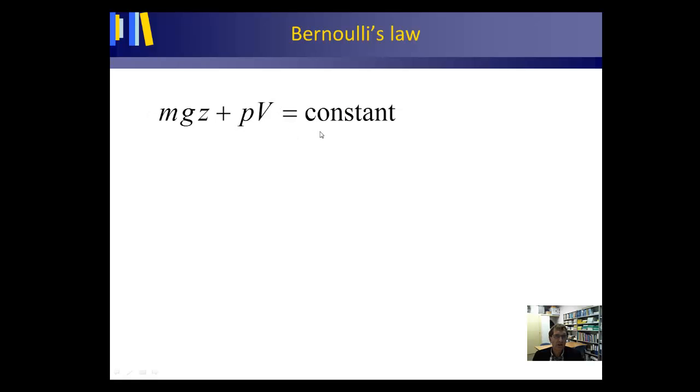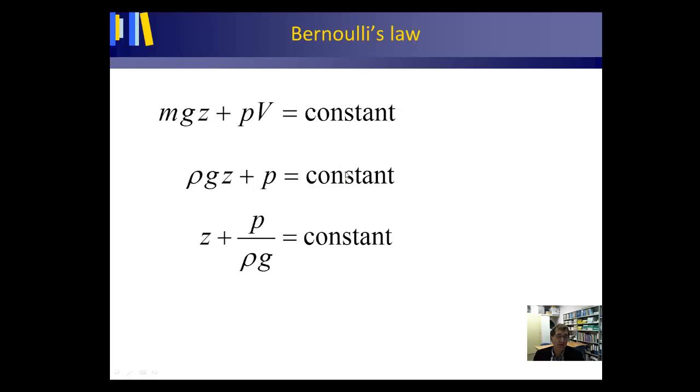So this is constant, as I just told you, and we can simplify the equation. We can divide all terms to the left and the right of the equal sign by the volume of the water. And so you could also say we're looking at a certain volume in the subsoil. Then mass, of course, becomes density, so kilogram becomes kilogram per cubic meter. These, of course, stay the same. And if we divide by volume, your pV term, of course, becomes p. And this is also constant. In actual fact, this constant is now divided by V, by the volume.